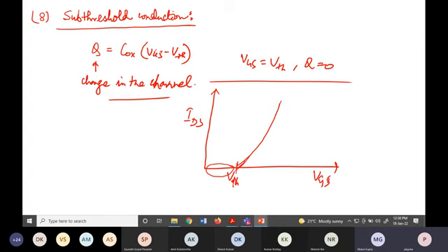But as we move to short channel or scaling down the FET, below VTH we will have current, and that current will be an appreciable amount. What it means is that the static power is no longer 0.